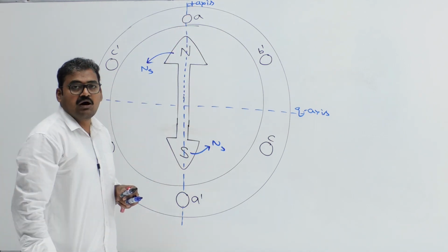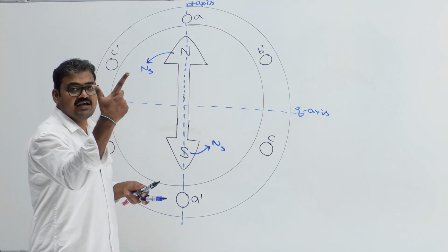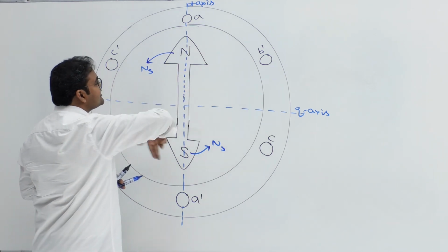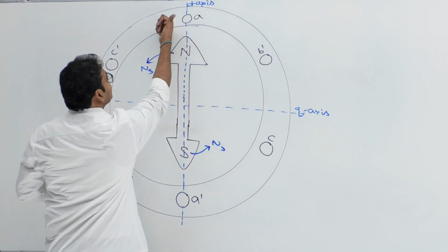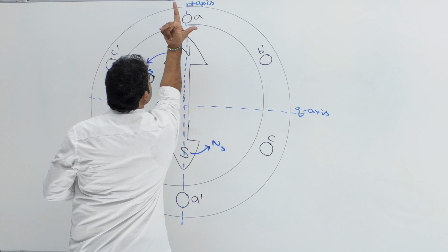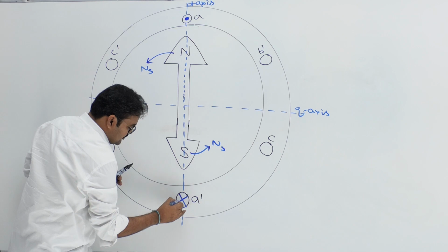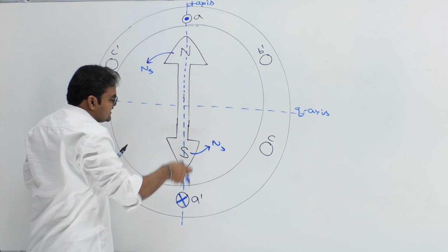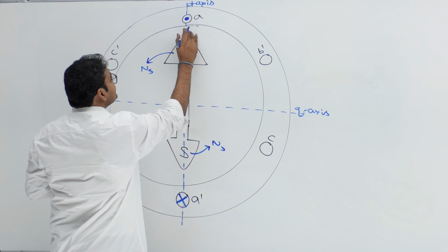How to identify the polarity of induced EMF? See, this is the 20th time I am discussing how to identify the polarity of induced EMF. Field is rotating in anti-clockwise direction. That means conductors are relatively moving in clockwise direction. So this conductor is moving to the right side. North pole will emit the flux. Induced EMF is out of the plane. And here it is going to be into the plane. These are the maximum EMF positions. Right now, phase A voltage is maximum. And assume this is the reference position, that means 0 degrees position.